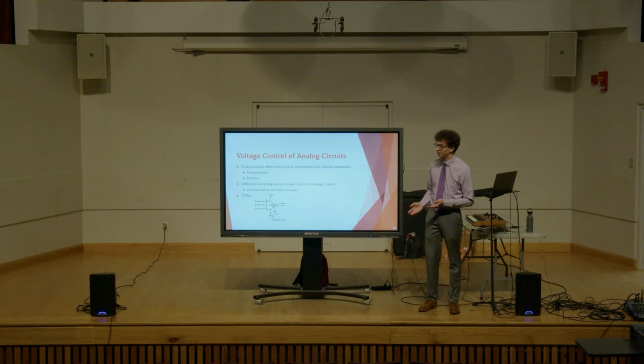After doing a lot of research, I found that this falls under the operational amplifier umbrella. For those of you who are familiar with electronics, this component measures the voltage difference across its two input terminals and spits out an output current proportional to that input voltage. But what's special about the operational transconductance amplifier, or OTA, is that you can provide it with a bias current that determines how much gain, or how much transconductance, which is amperage divided by voltage, is applied to the input voltage difference.